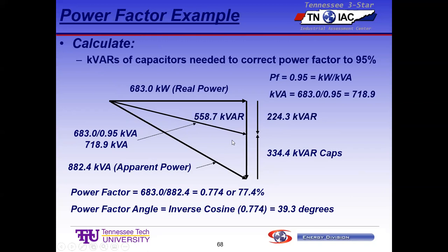The only thing beyond that that really saves big money is if you need the capacity in your MCC, your motor control centers. The power feeds come into the MCCs, and the MCCs feed a bunch of different loads out there. They're in the electrical rooms of the plant. A big plant might have 5 or 10 MCCs. So the big power feed comes in, and then each MCC gets fed separately, and then from the MCCs, it goes out to the loads.